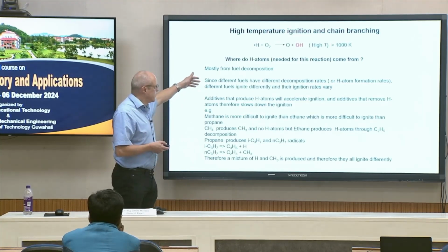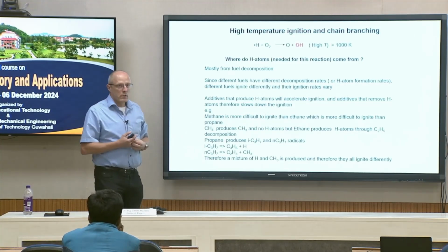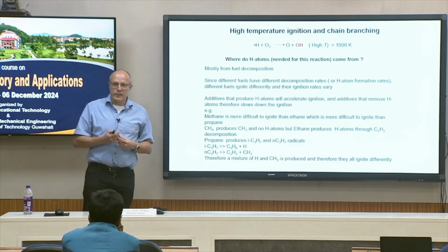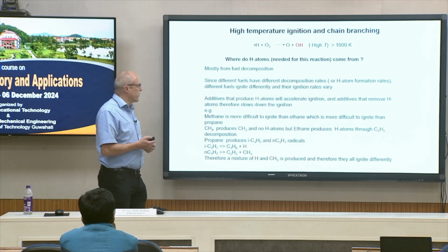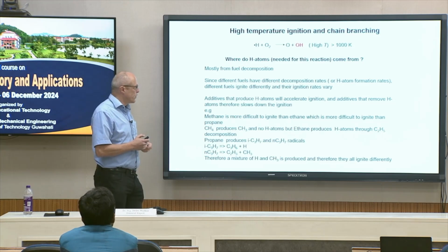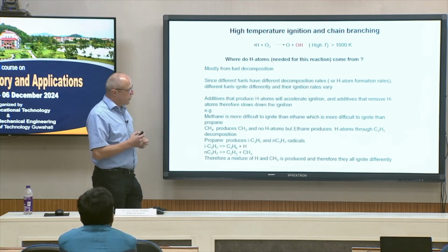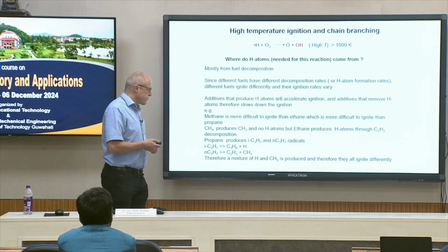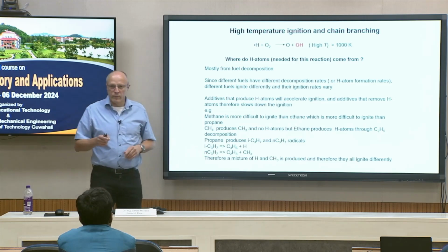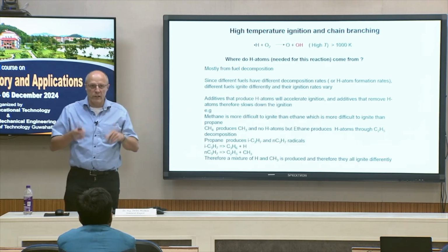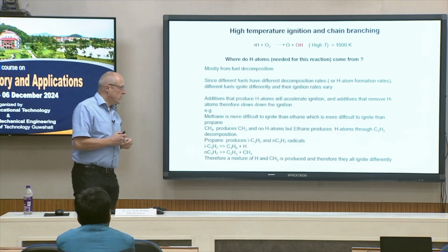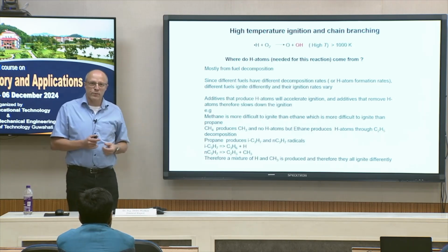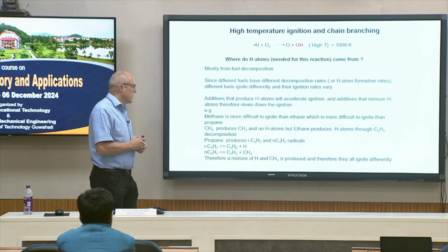So of course different fuels have different decomposition rates. So we see different ignition delay times for different fuels due to this different H atom formation rate. So for example, methane, C plus 4 hydrogen atoms, it's very difficult to ignite because it's difficult to abstract the first hydrogen atom.